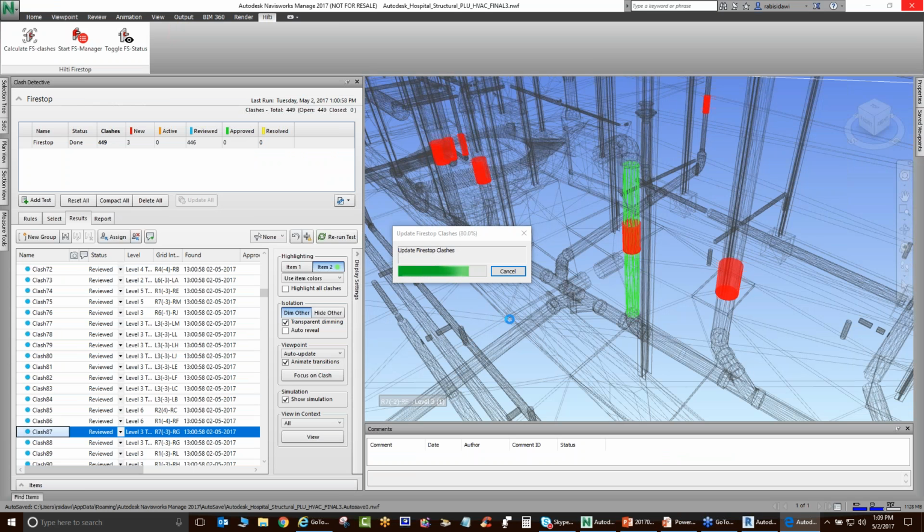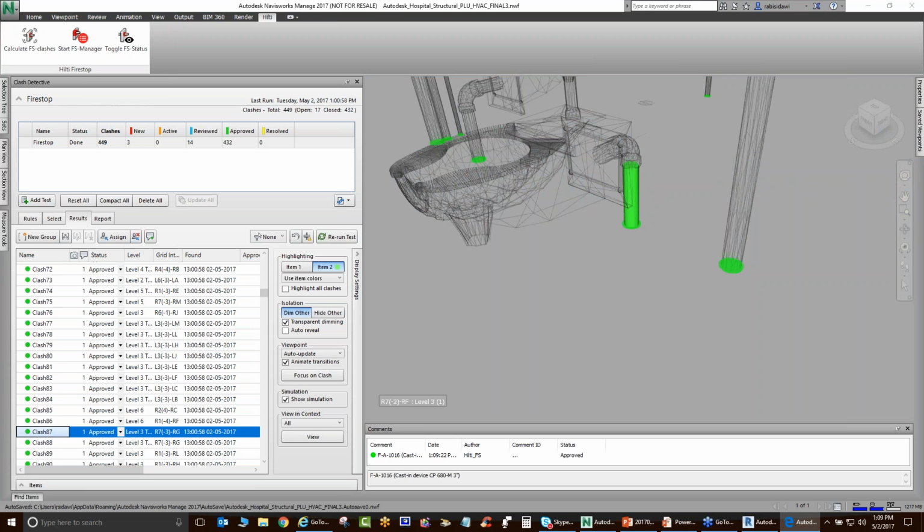and this will update those penetrations from red to green or blue or yellow, depending on the choices that we have made earlier. Here we go. So the penetration that was here for this particular water closet was red before. Now it's green, which means Navisworks has found a valid solution for this. We'll go ahead and save this NWF file in Navisworks, and then switch back to our